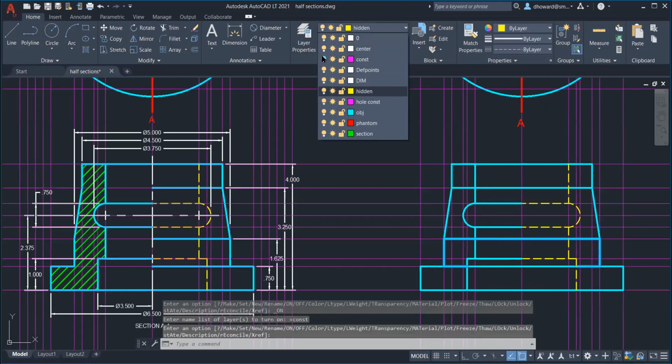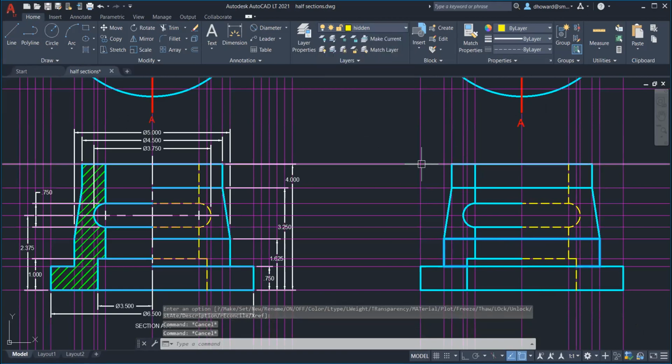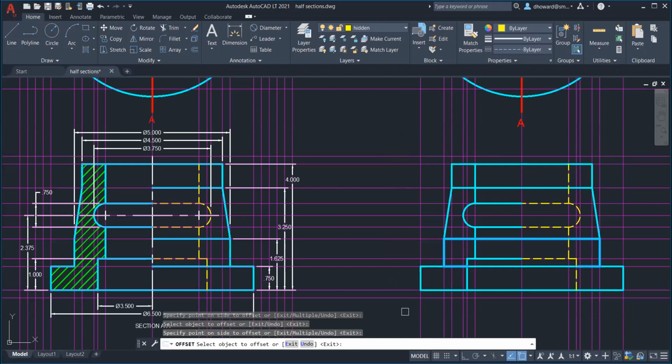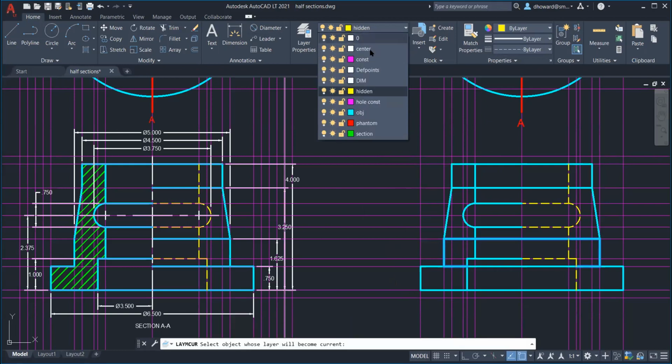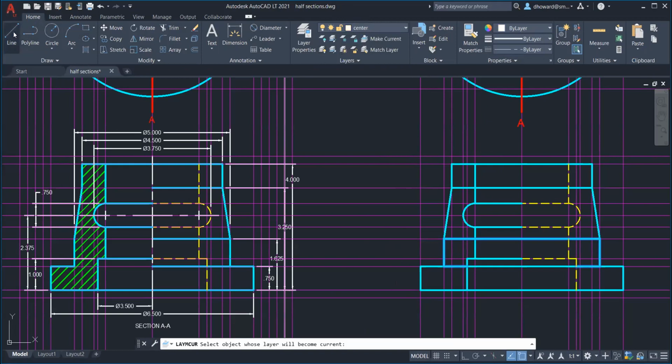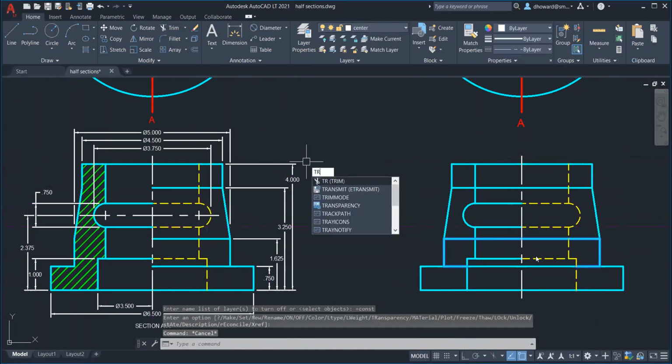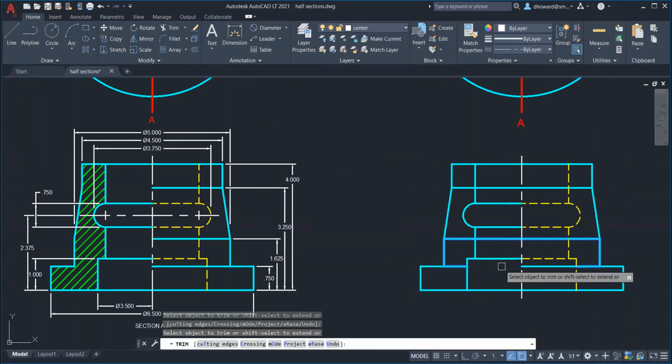I'm going to put my construction lines back on and do this offset of 0.25 so that I can correctly draw my center line. And that will make things a little easier when I do the trimming. All right. Center line's in place. Going to turn the construction lines off, and now I can trim this stuff out. There we go, without any problems. There it is.